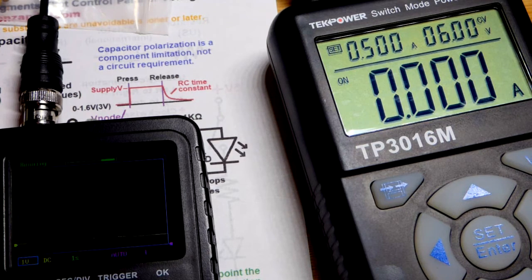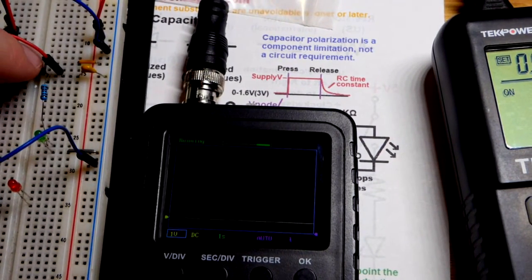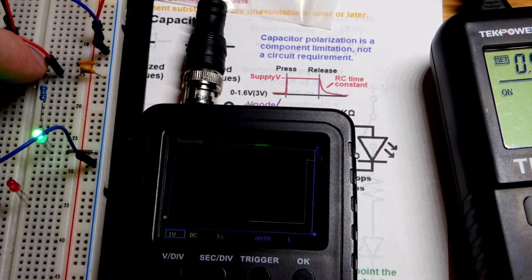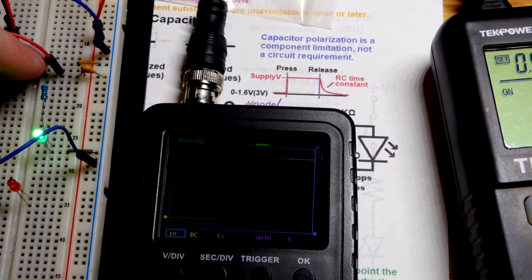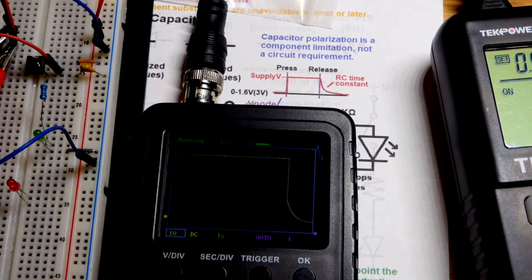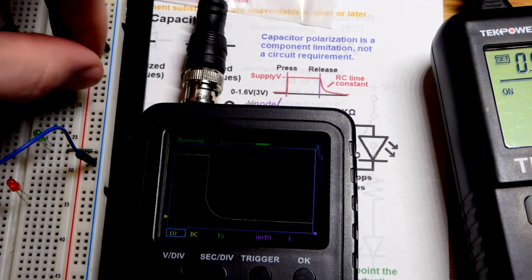And so what I'm going to do is we still have the little capacitor there, about half of a microfarad. So very, very small amount of capacitance. But you can see I press the button there. We have that voltage jump up there. So that should be about 6 divisions. 1, 2, 3, 4, 5, 6. It's easier to see it in person than through the camera. And now when I let go, there you can see a drop and a curve right there. So it is pretty dramatic, as you can see right there, because it is a low value capacitor.